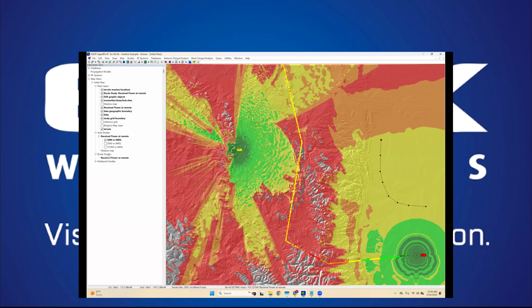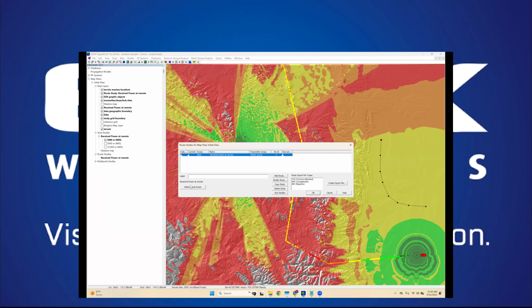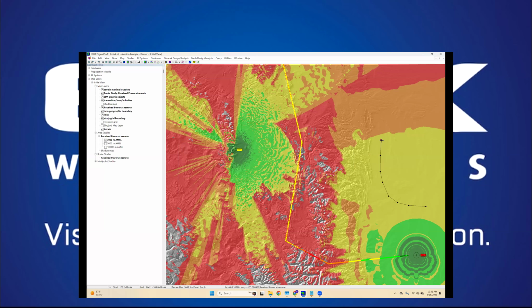When you go in and define your study route for your route study, you can check use lev, use that .lev route file, and it'll update the elevation at each little point along the study path. So it's going to interpolate. It'll make a straight line in between your elevation changes.